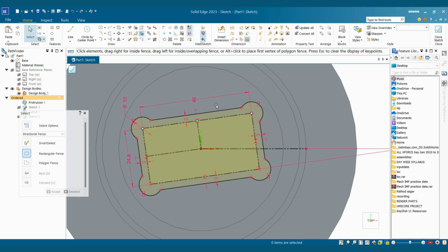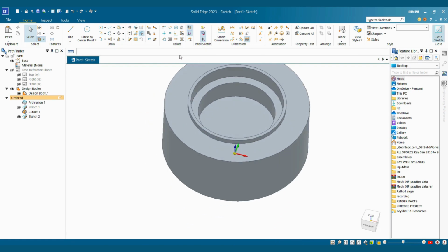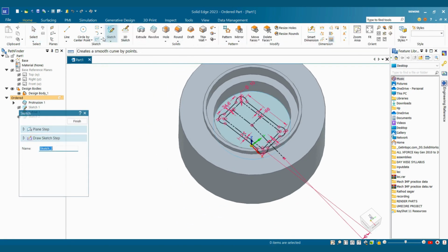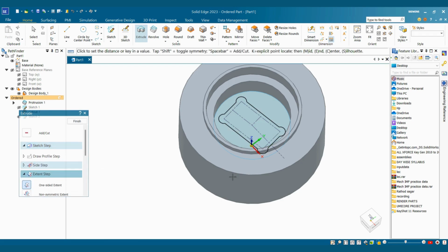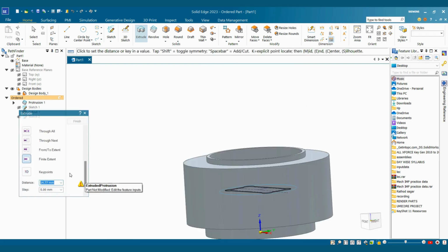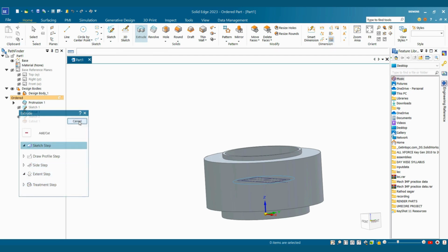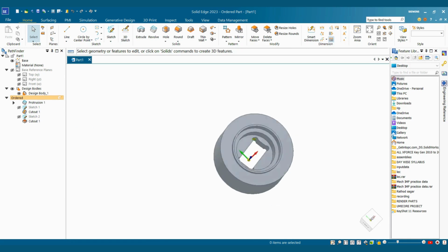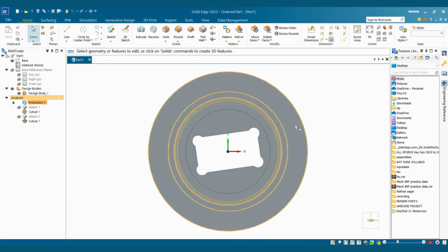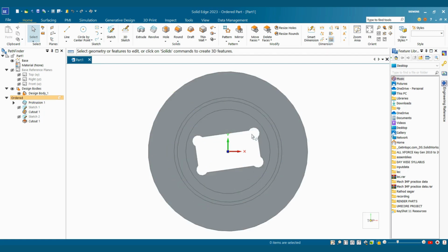So next thing we are going to do here is making this a cut extrude. Say close sketch and go for the features and say extrude cut. So in extrude we are going to select cut option, select the profile you need to cut, say OK, and this cut will be through all. So in extend step we are going to say through all. So the direction at bottom side and say finish. Now hide this sketch. So we can see here in top view this part has been made having 8 degrees rectangular cutout with corners as rounded here.